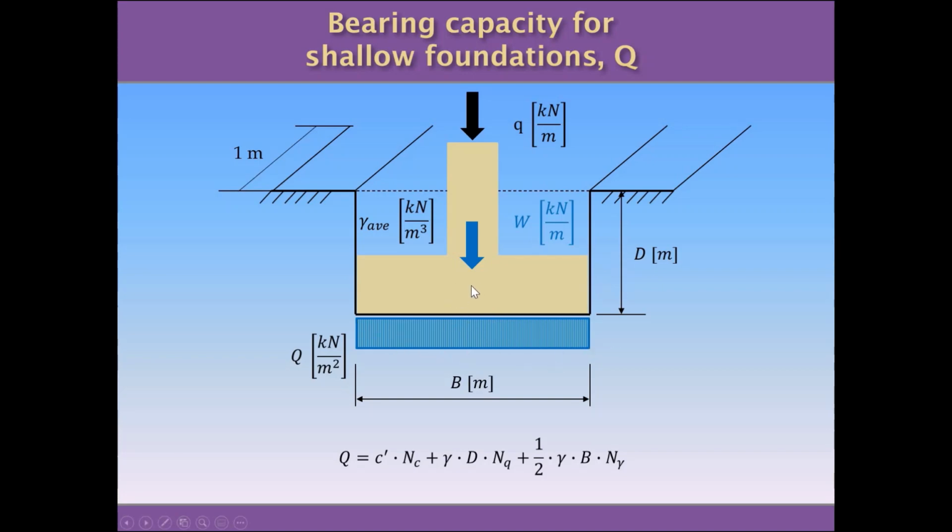So the contact between the foundation and the soil will generate a reaction from the ground that is going to have this shape. So it's going to be a uniformly distributed load. This is not exactly true, because in reality, because of the characteristics and the properties of the soil, this distribution will certainly be non-linear. But because we need to simplify the calculation, we're going to use this distribution. And anyway, the values we are going to obtain are sensible and can certainly be used to design and to verify foundations like this.